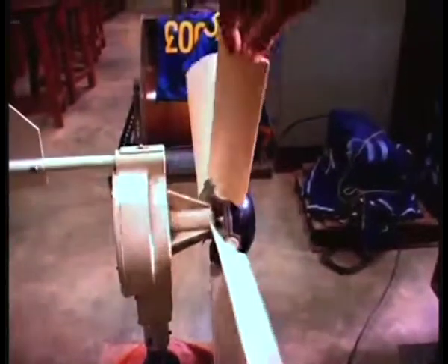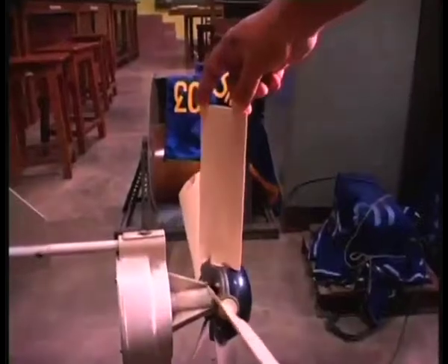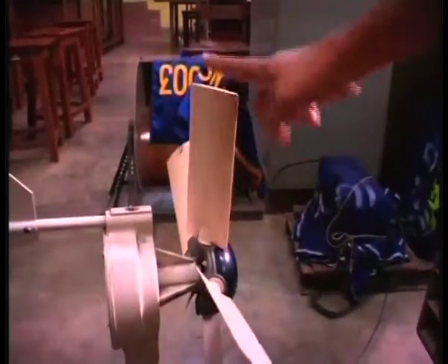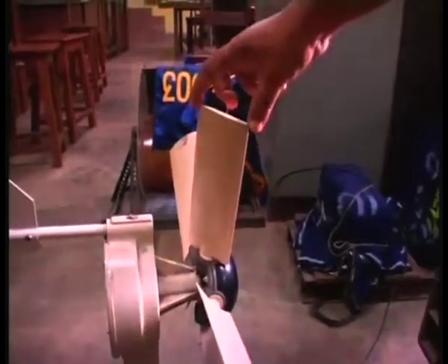What you can see now is the airfoil profile, which is, as you can see, as it is zooming back, you can see that it is inclined at an angle to the plane of rotation. And actually this is the plane of rotation, and these airfoils are inclined at an angle. So the chord is inclined at an angle to the plane of rotation, which is the pitch angle. So as you can see, the wind is blowing from this side and it is rotating this way. So the relative wind is along this direction, and this pitch angle has to be so aligned so that the blade chord is aligned to the direction of the relative wind.